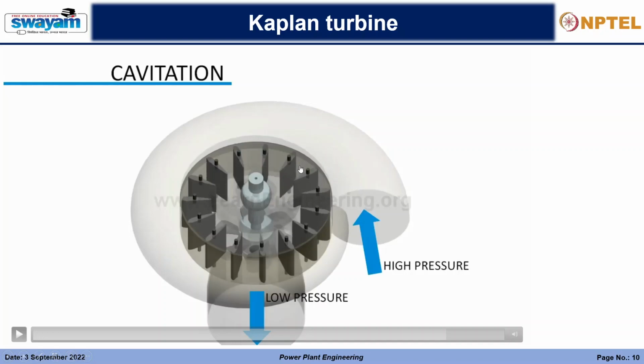So by this angle, the tangential component of the velocity, which imparts the rotating effect around this longitudinal axis, is reduced. Hence the water is more prone to go in axial direction. So that is one of the main contributions of these guide vanes.